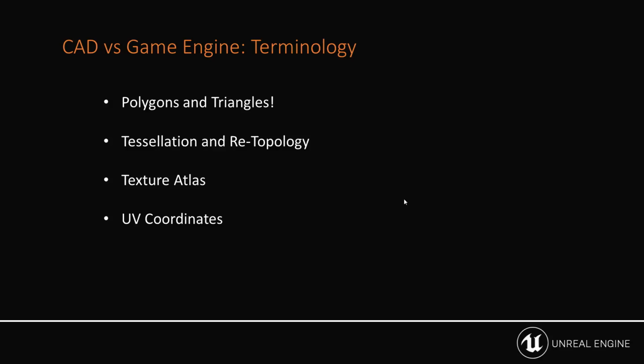Once the UVs are provided and placed properly and clean, things like logos and details from different types of textures, tire details on the rubber, whatever it may be, UV coordinates are going to produce that accurate detail for you. If you don't have UV coordinates, you're not going to have texture. If you don't have clean UVs, you're going to have a messy texture. So UVs are very important, especially when it comes to visualizing data with imagery as textures.